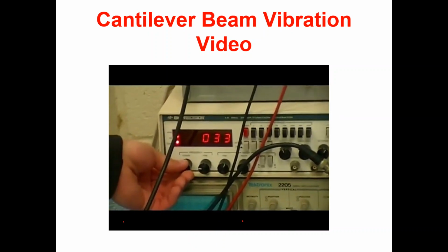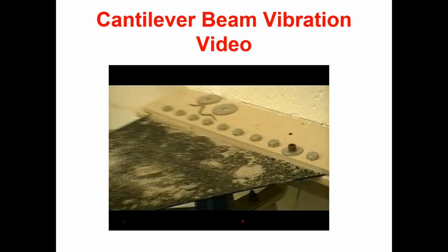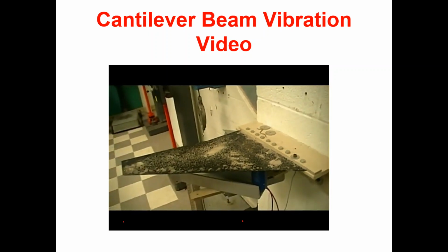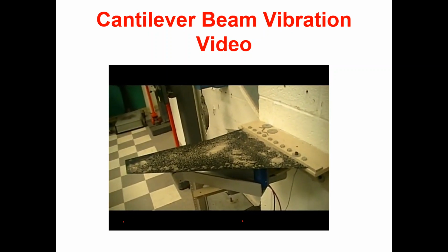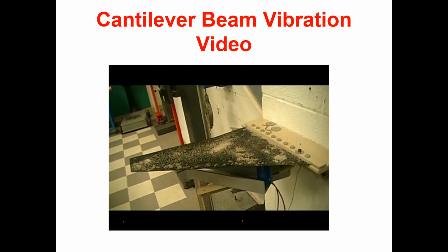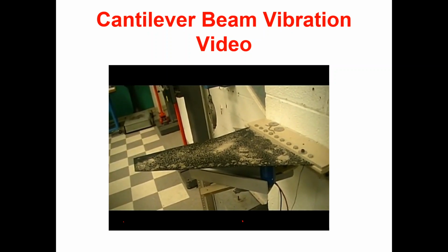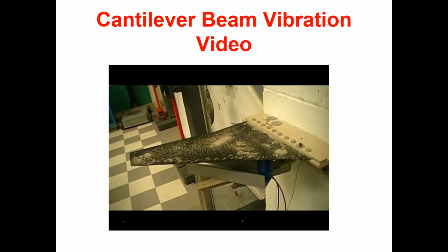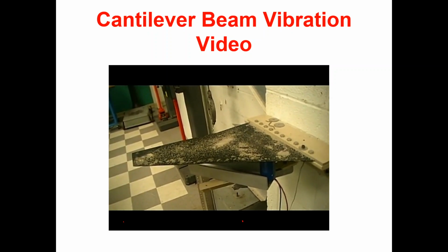Using the coarse adjustment knob, we'll reach 34 Hz, and then use the fine-tune adjustment knob to reach the resonant frequency. Telltale signs that we've reached the resonant frequency include maximum deflection of the wing tip, as well as the formation of the nodal point, much like the cantilever beam experiment. When the sand begins to move, you know you're on the right path.